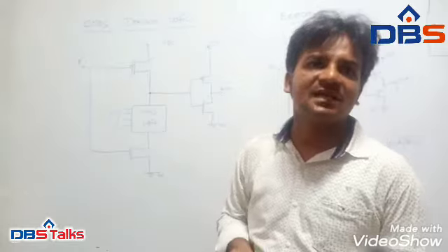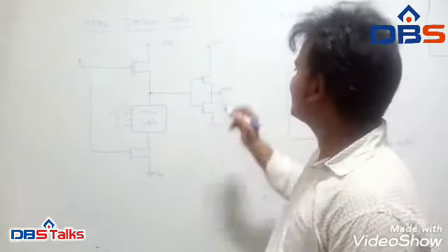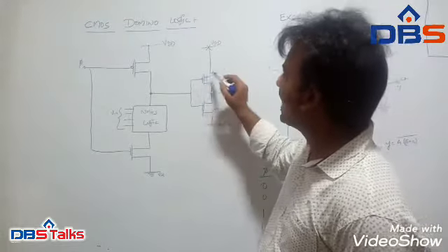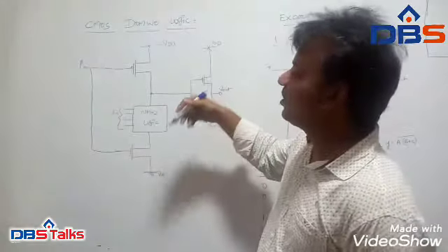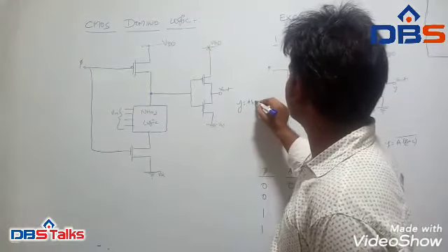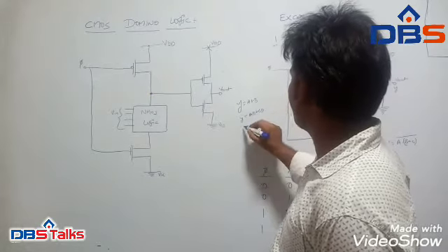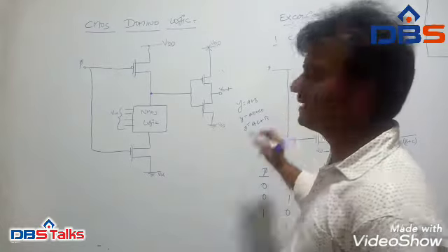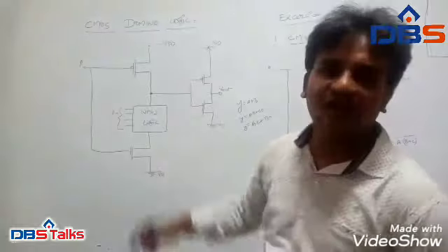Next, non-inverting structures are possible because of the presence of the inverting buffer. At the output of this circuit, we are adding an inverting configuration. Due to this, non-complemented functions are possible, that is y is equal to a plus b, or y is equal to ab plus cd, or y is equal to ac plus ba, like this. So we can perform different non-inverting functionalities by using domino logic.